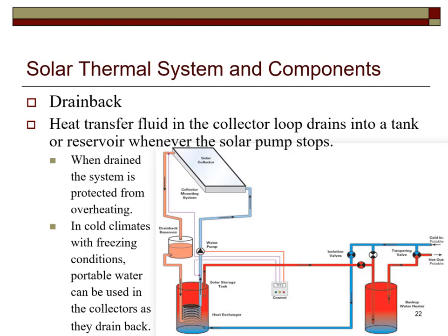During the nighttime or on cloudy days when the temperature at the top of the collector is not warmer than the water in the storage tank, the pump does not come on. If the temperature in the collector and/or the reservoir becomes too hot, the pump shuts off and the liquid drains back out of the collector. The system also demonstrates the most popular storage tank arrangement. The storage tank, which is heated by the solar thermal collector, supplies preheated water to the standard water heater.